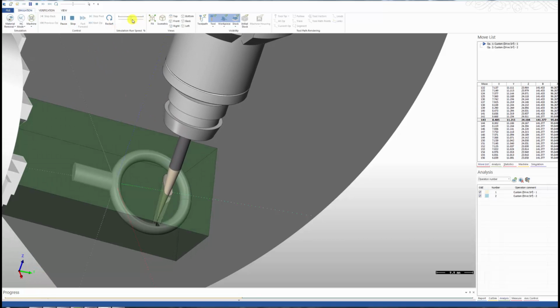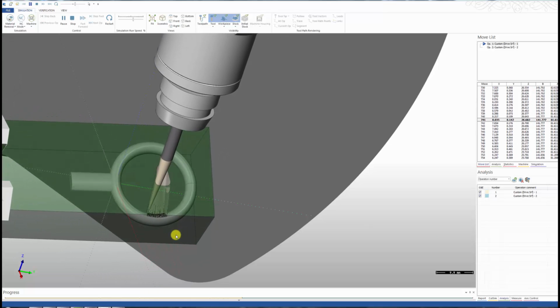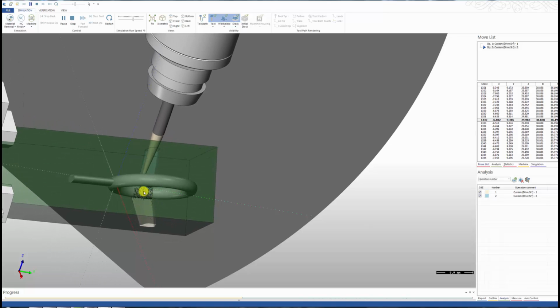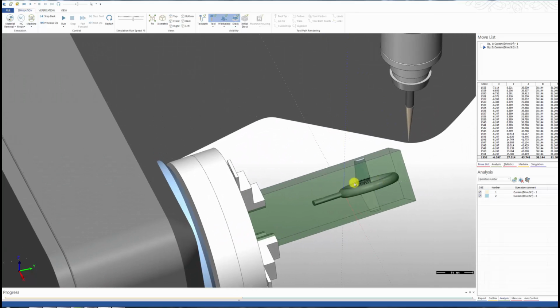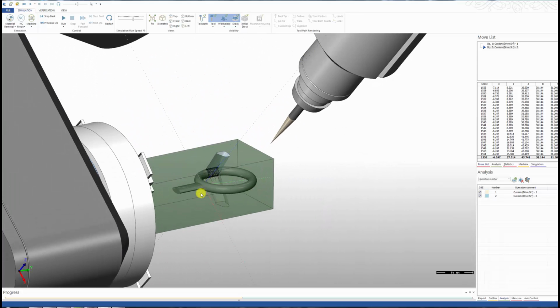Here's our side A, and here's our side B. You will see that we were able to cut this little engraving without having to specify complex boundary curves, determine which angles of approach we need, etc. We could have done it with parallel cuts as well, but it would have taken us considerably more time than simply creating a drive surface and letting the machine and the program figure out the rest.